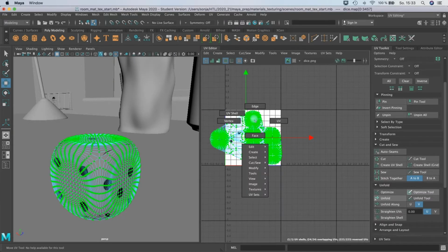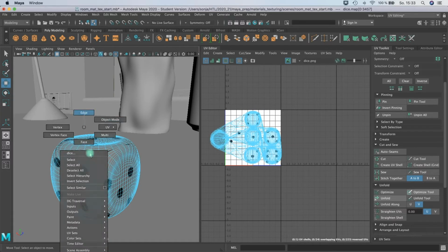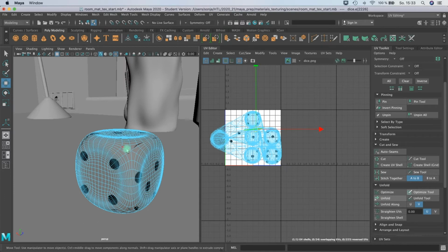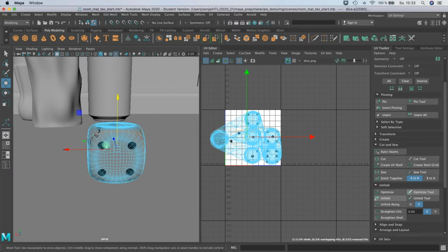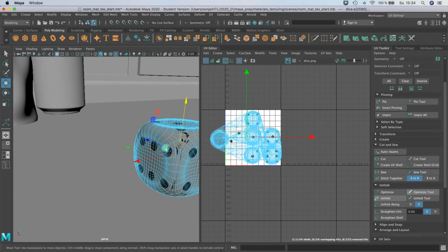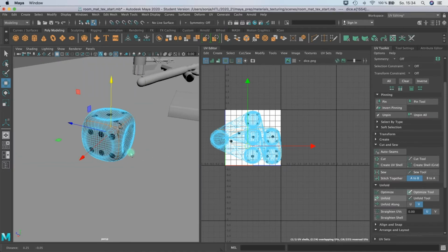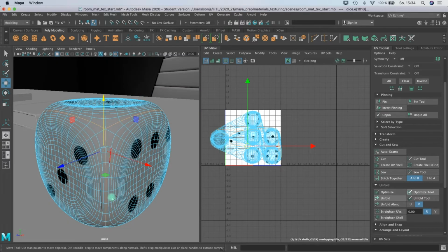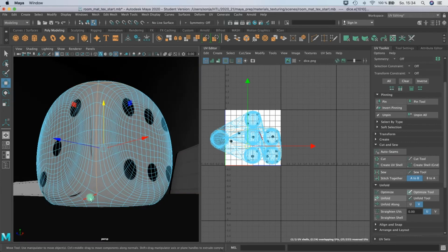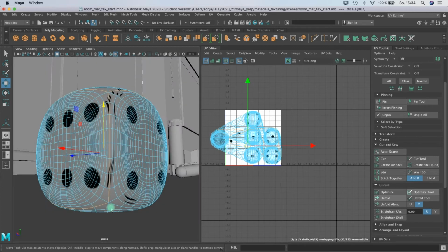So, and now we go to the edge mode, and I'll show you another cool thing. You see here there's a point where the lines all go to one star, and I press Shift on the keyboard and I double click here all the edges. When you press F on the keyboard, you can frame the current selection and it will be easier to select the stuff. So then I need one here and here and another one here.